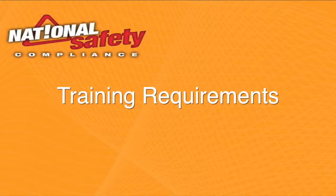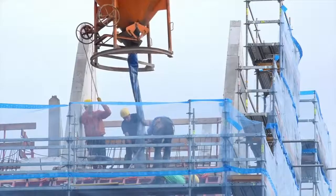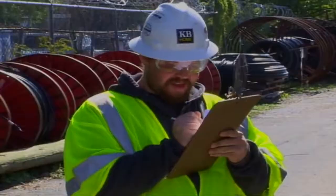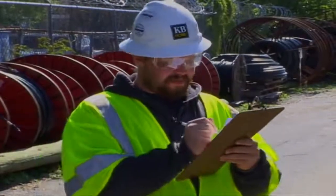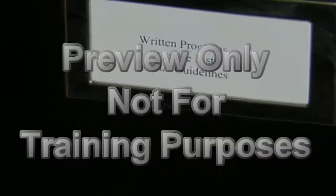There are 2 groups of workers that are associated with scaffolds: those that erect and/or dismantle the scaffold, and those that use the scaffold for work purposes. OSHA requires job-specific training for both groups of employees. All pertinent training information, including dates, subject matter covered, names and times, should be documented and kept on file in a location decided upon by your employer.